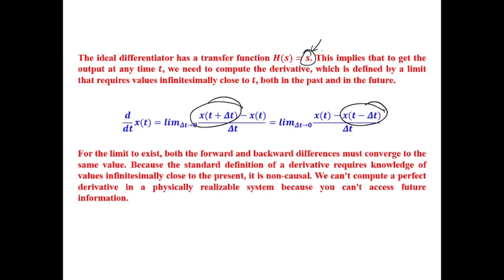Okay, and if you are left with extra s components, it will make the system non-causal, and since it will be non-causal, your filter will become unrealizable in the physical domain. Okay.